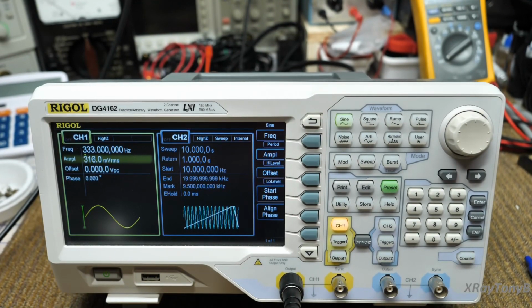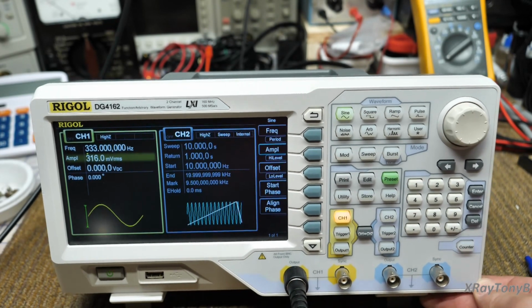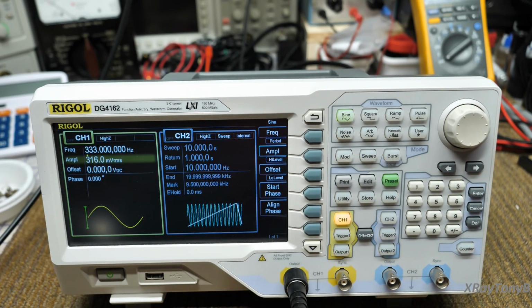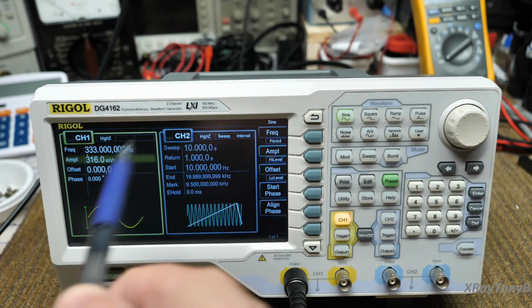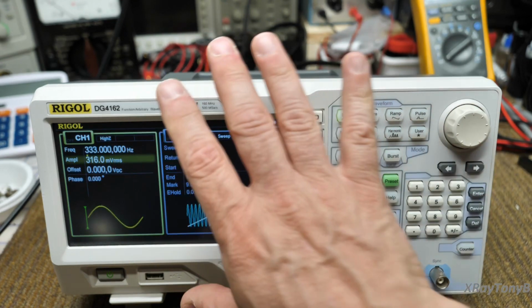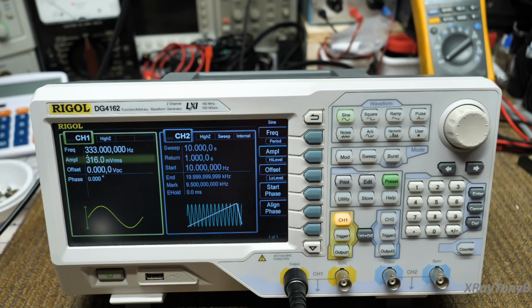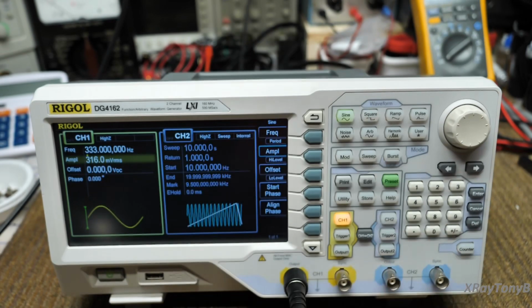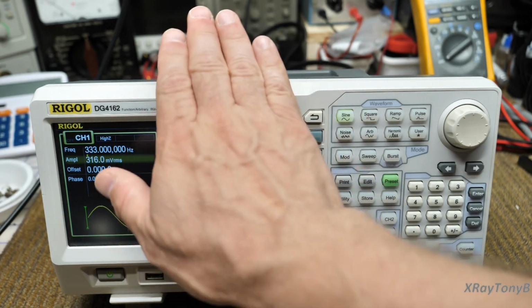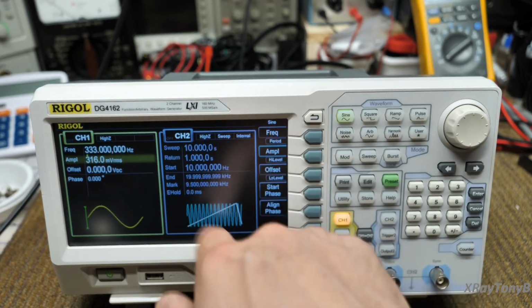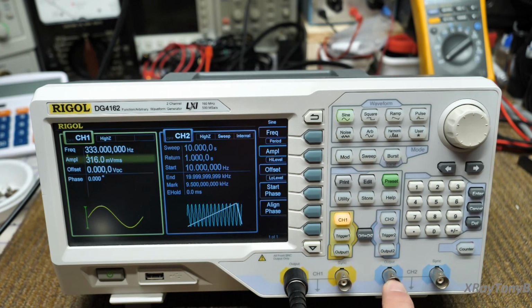Okay, we have an oscilloscope connected up to this, and before we go up and look at it, this is called a two-channel signal generator, and really all that means is there are two, just think of this as two signal generators in one case. So you have the yellow section, which is channel 1, and the blue section, which is channel 2, and they're both independent of one another, and I can generate two different signals at the same time. So for what we're doing, we only need to really worry about one, because we only need one signal. Okay? So whatever I'm doing on this channel, I can do the same on this channel and output it from this connector.